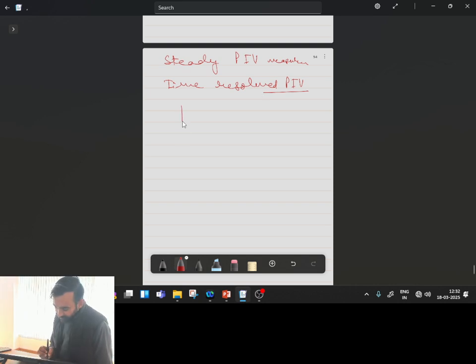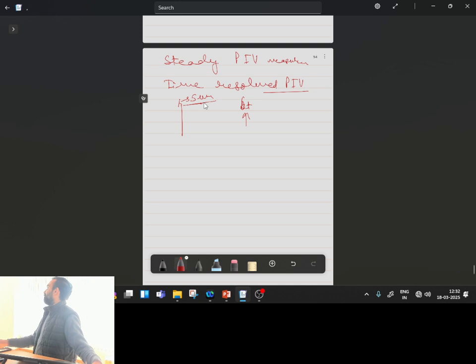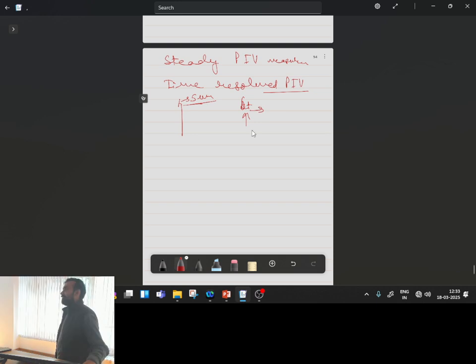Now, say your thickness of laser sheet is 5 micrometer. You will choose your delta t time step in such a way that between two consecutive frames, this much distance should not be covered by the particle because of the velocity field. Is this one clear? So the selection of delta t is also an important aspect.